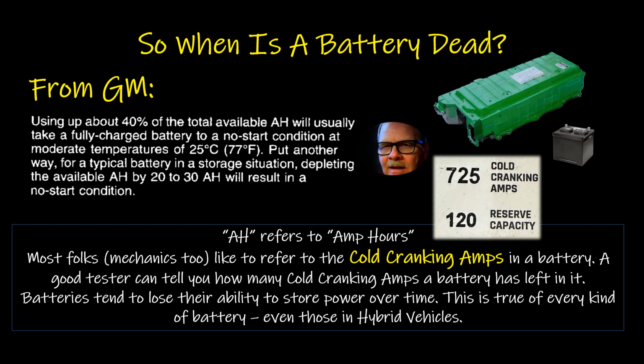Now, I was talking about it being a reservoir of energy a while ago. What it amounts to is, and I've mentioned this before, when you first buy a battery, let's say it's got 850 cold cranking amps. Well, if you check it a year later, it'll probably have 750 or something. And every year it's going to lose about 100 cold cranking amps on the average. That's been my experience. And if you keep that thing 6 or 7 years, it's going to be down to the point where it will barely start the car.